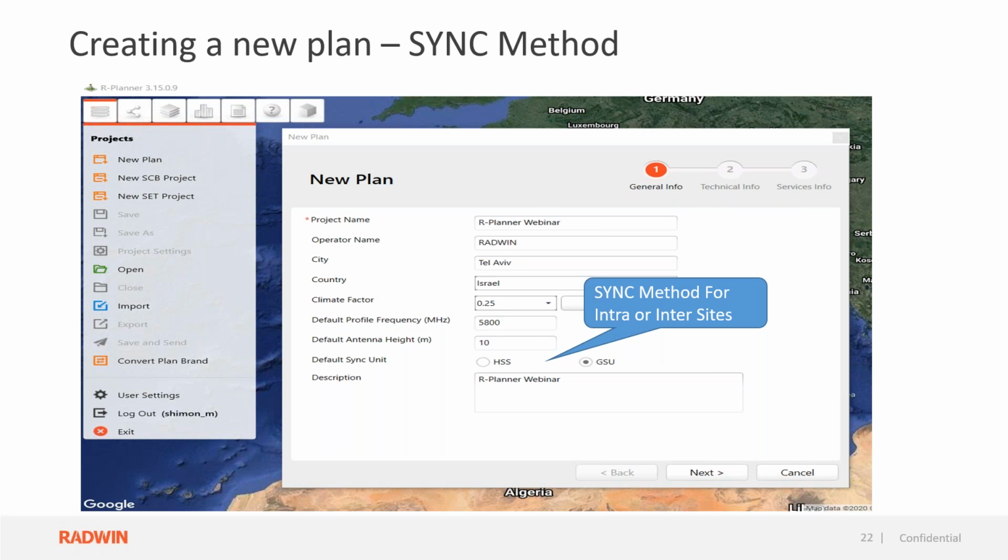One device, one ODU must be the master. If it is a GSU, GSU becomes the master. If it is point-to-multipoint and there is a JET DUO or JET beamforming, the JET has integrated GPS, and the integrated GPS is the clock for all the deployment of point-to-multipoint.